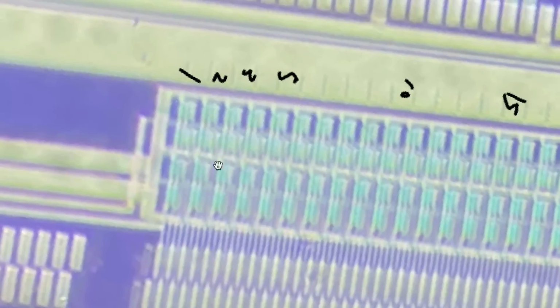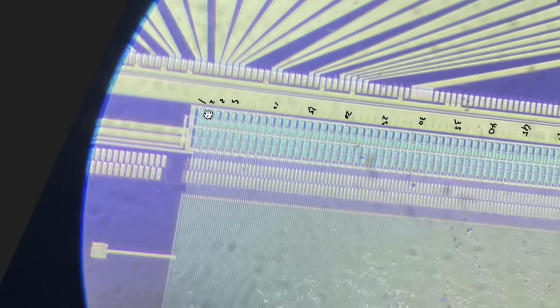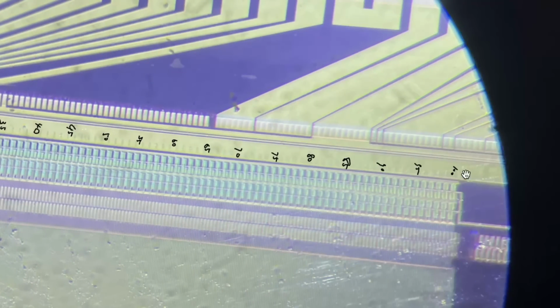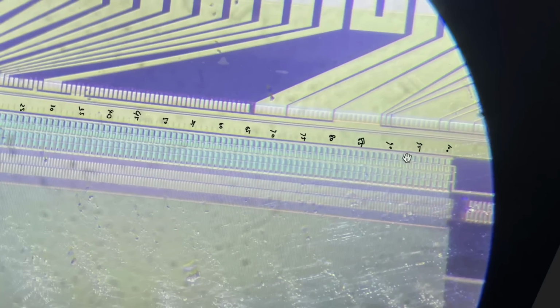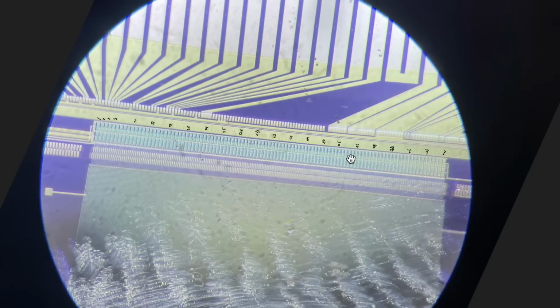And then we focus on the middle part. Similarly, I counted these groups. I'm not entirely sure what they are, but each group is 4 pixels, so I can count in these groups. Entirely I count 100 groups, so it means there are 400 lines or 400 pixels. That gives us the entire chip capability of around 400 by 320 pixels.